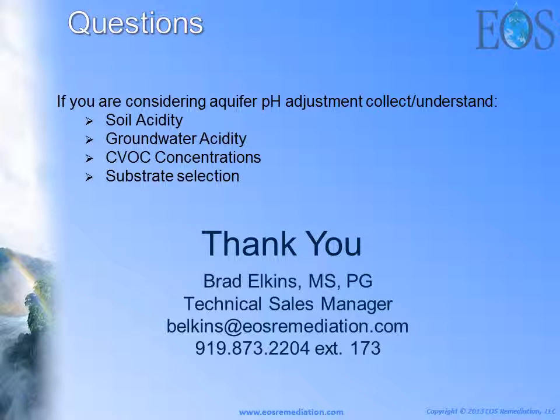As you are thinking about doing in situ bioremediation projects for your site, and you're interested in aquifer pH adjustment, I would urge you to strongly understand your site's soil and groundwater acidity. You could go out during your characterization, collect a soil and groundwater sample, and submit them to a laboratory, and they can tell you the acidity of that material, so how much base you're going to need to add to adjust the pH of that aquifer. That's going to be very important for calculating the amount of whether it's CoBuff or sodium bicarbonate or whatever you choose. It's going to be important to understand how much you need to add, and that acidity value will give you the ratio you need, so you know how much material to apply.